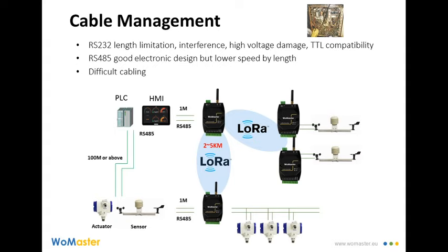Now, in order to extend the distance, the user just adds the LC and LM between them with different Modbus IDs, and they don't need to change the polling Modbus ID in the application. HMI is still polling the ID 10 to get the sensor data. The whole application can be upgraded in this way.